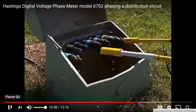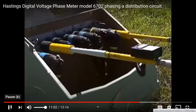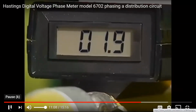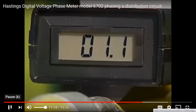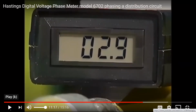Connect the end to the cable to be tested, and energize that DC high pot. Now we got a good initial current flow. It's accepting the charge. It's dropping to a low value. It's obviously a punctured cable. It's dropping back off again. Okay, yes, it's a punctured cable.